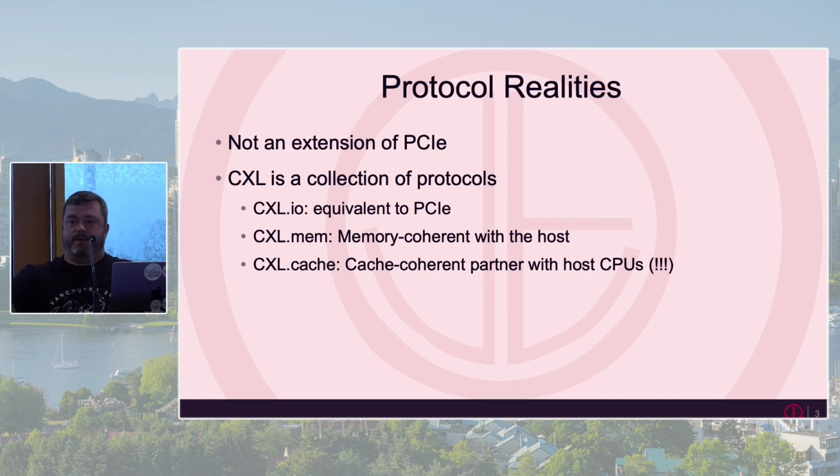CXL comes in and busts open the wall down like the Kool-Aid man and says, I want to also be part of the cache coherency protocol. It really opens up a lot of interesting use cases. Like Srijit was talking about, you can now have your device actually own the line. The line actually doesn't sit in the CPU cache somewhere, you own the line. And the CPU is snooping you, saying, hey, do you have an update to the line? Do you have an update to the line? So a lot of really cool use cases you can build around this, but it's also very, very complicated, right? Now you are participating in a cache coherency paradigm that has been typically behind a closed off wall. And if you screw it up, some very bad things happen.